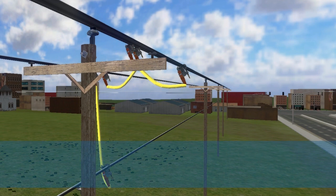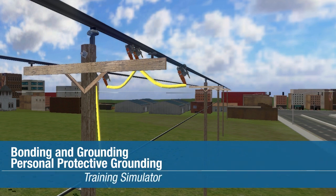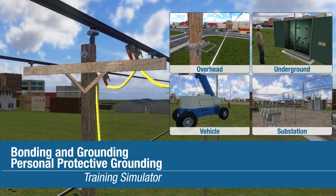This video will introduce you to the function and features of 3D Internet's Bonding and Grounding Personal Protective Grounding Training Simulator. This training solution is designed to train power line technicians in the methods used to isolate, test, and apply protective grounds on de-energized electrical facilities prior to beginning other work. The scenarios include typical procedures involving overhead, underground, vehicle, and substation grounding conditions.